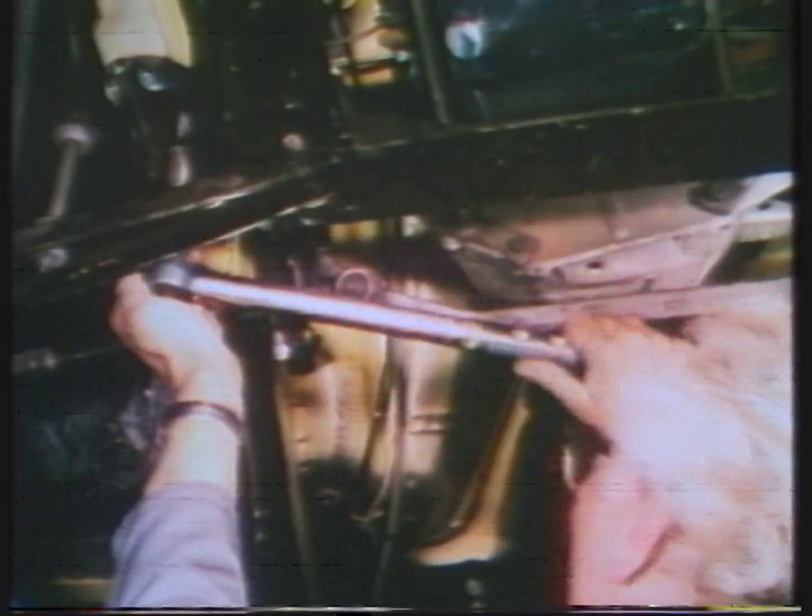Then retighten engine mountings and the hanger brackets. Also check that engine and suspension mounting bolts are to the correct torque loading. The details and figures can be found in your workshop manual. If the engine mounting rubbers and suspension and engine mounting bolts are correctly torque loaded, then check radial and lateral runout of the tires and entire wheel assemblies, as was done for the previous problem. Then rebalance and road test.